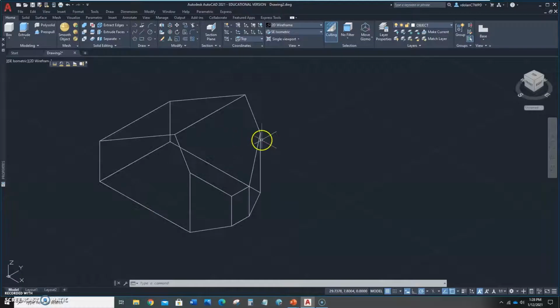So we need to change our UCS, and using this method, we must keep changing our UCS whenever we go to draw anything. Okay, if I were going to draw a hole, for example, over here on this edge right here, if I go up to circle now, draw a hole, okay, obviously it's on the XY location, so I'd have to go up here and I'd have to go to the right view, okay, and then, whoops, I'd have to go to the front view, sorry, okay, and then my hole would be in the right location.